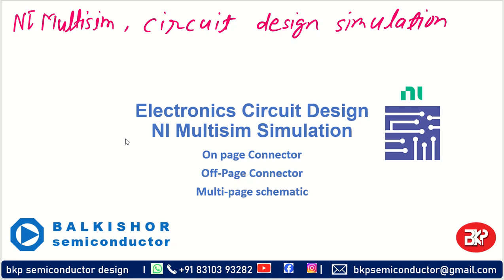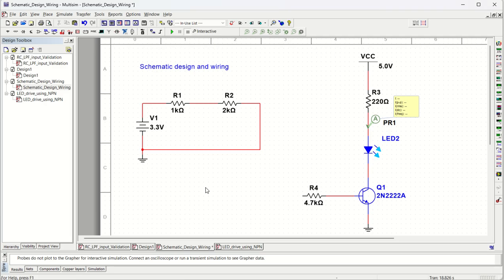Namaskar, my dear friends. Let us talk about how we can design complex circuits in NI Multisim. There are a few occasions where you need to utilize multiple pages, more than one page. You need to use on-page connectors, off-page connectors, and there are various other parts that you require in the schematic design. So those designs and techniques we'll try to find out, and we'll do those things here, right? So let us open Multisim.